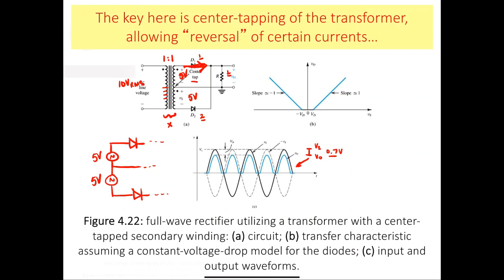First off, there's going to be a different point at which the inverse voltage is applied across D1 and D2. Let's take a look at D1 first. So D1 is going to be blocking when the input voltage is reversed in polarity. And as you can probably see from the picture, the peak of that inverse value will occur at the peak of Vs. Now, let's ask ourselves, so what is the inverse voltage applied across that diode at this instant right here, which we can call T alpha?